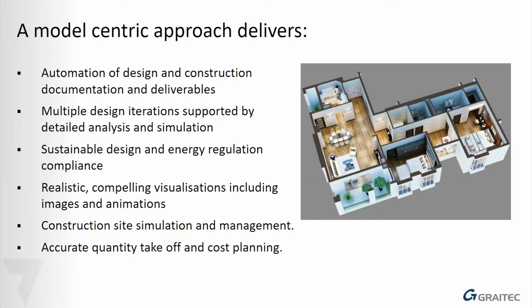We've got sustainable design for energy regulation compliancy. So the three-dimensional model that we will be creating, when we actually create that, there's nothing to stop us then looking at doing energy analysis on that. Because of the changeability within a BIM model, we can make very quick changes or very big changes very quickly. If, for instance, I realized I had to increase the thickness of all my exterior walls because I needed to add extra insulation, I can do that very, very quickly. And we're talking about a change that would happen within a matter of minutes rather than a matter of hours or days in traditional 2D ways of working.